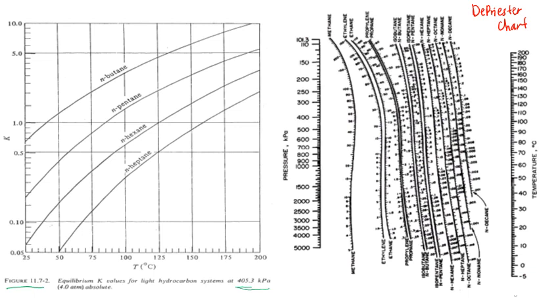If you notice, there are about 4 different charts with different temperature ranges, different units of pressure and temperature, and different ranges of pressure. So if you are not given a chart like the one on the left hand side, where you can easily read the K values at different temperatures, because this chart at the left hand side here is conveniently made for you at this pressure,